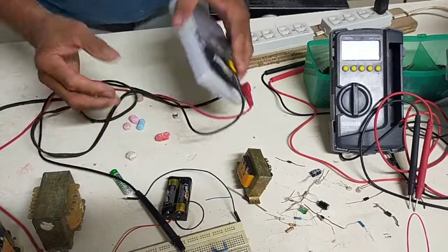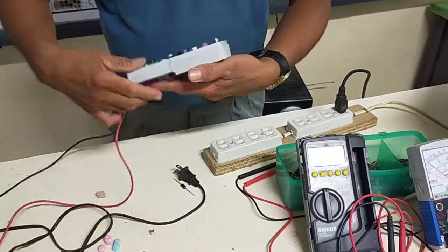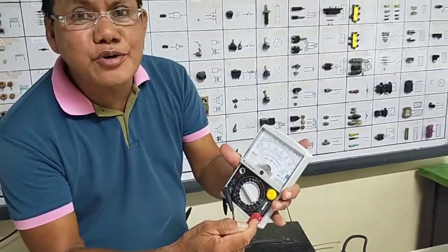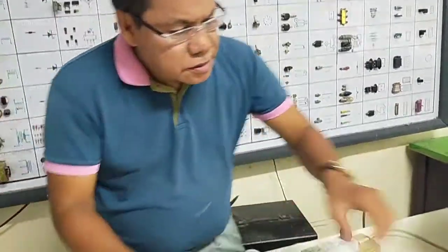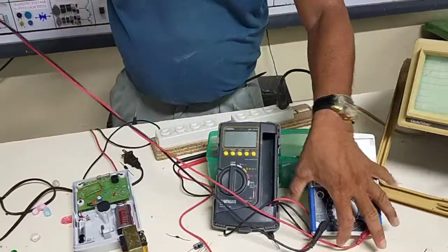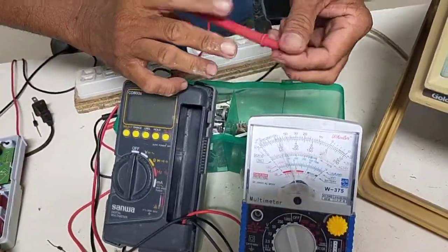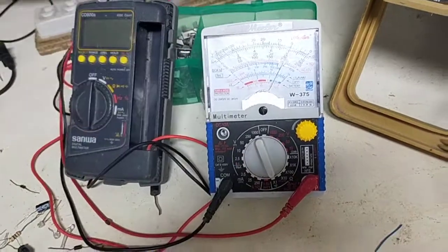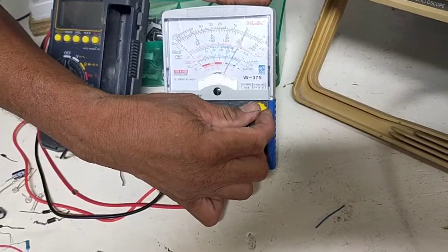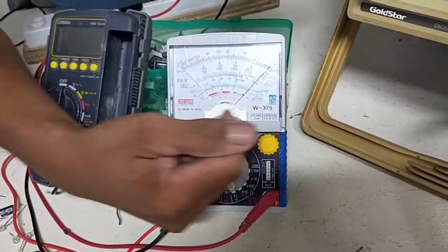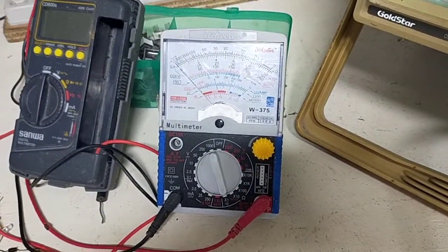See? So, this would mean that this battery is intended only for the ohmmeter. And we can tell that this is negative for the ohmmeter and the black test pad is positive. Because if we try to get the continuity using the times 1 ohm range, it is advisable to always set the ohmmeter deflection pointer at 0 level. So, set it to 0 using this ohmmeter zero adjuster, for sure, to have an accurate reading.